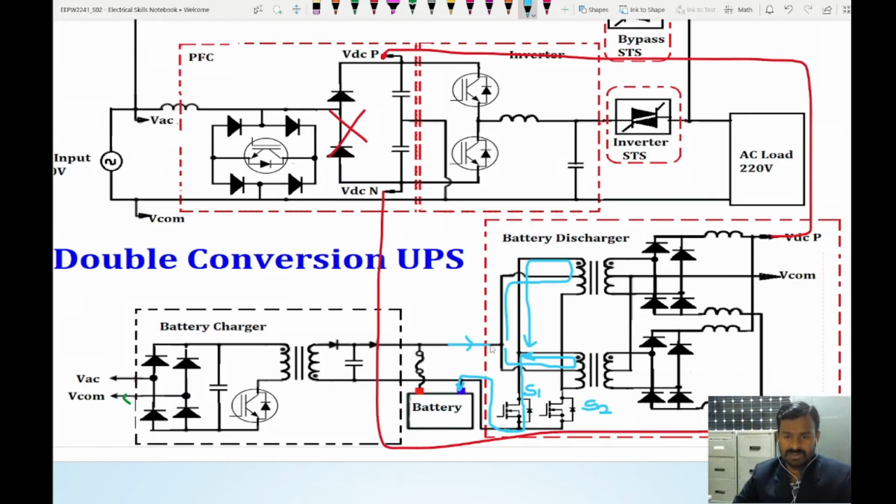So it will start from here. It divides here. A partial amount of current passes through the upper portion of the transformer coil and comes back. Similarly, the remaining current flowing through here also passes through the upper portion of the transformer coil and comes back. It is added at this junction and returned to switch 1 through this coil. When current flows in this part, there is an induced voltage here, and this will be fed to the DC link with the help of these rectifying units.